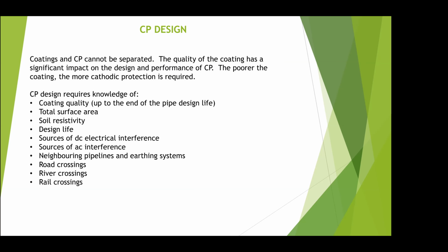So now we come to the CP design aspect. As I mentioned before, you can't separate coatings from cathodic protection. The quality of the coating and the performance of the coating has a massive impact on the CP design. And in order to do this design properly, you need to know about the coating quality up to the end of pipe design life. And the greatest amount of coating damage occurs during installation. Transportation and installation is where most of the damage occurs.